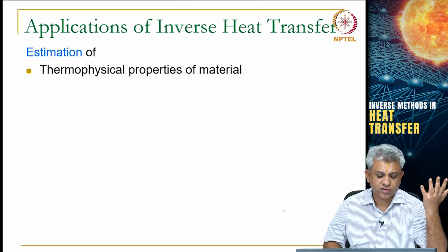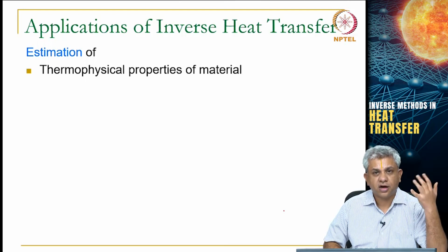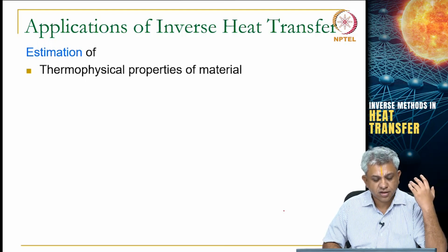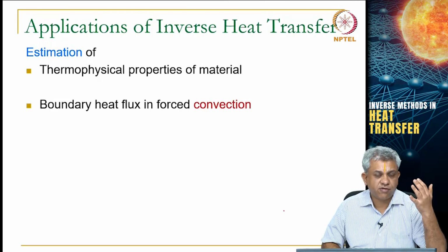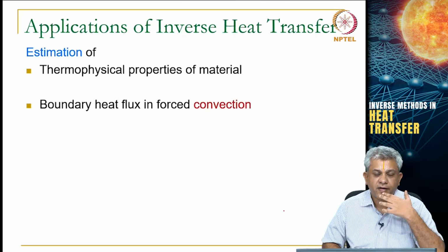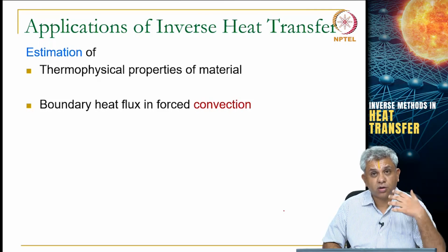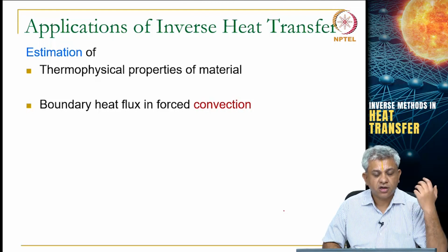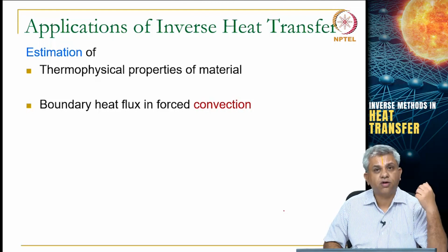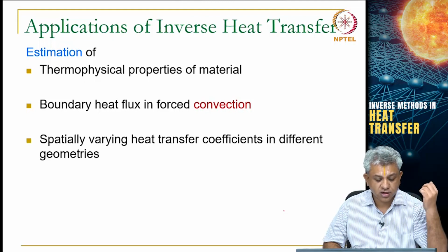So, estimation of thermophysical properties of a material like conductivity, etc. So, that you can try to do, as I talked earlier. In fact, a straightforward important industrial use of inverse methods is there. You want to find out the boundary heat flux in forced convection. That is an example of how you find out the heat flux given all the other details.